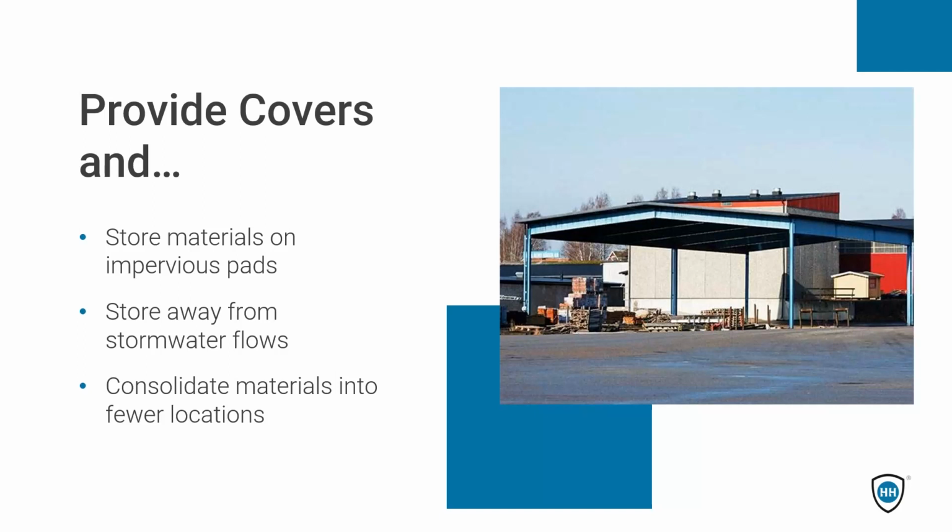For example, containers that are stored outside, portable tanks, generators, equipment that is just commonly messy. Anything that you can provide cover for is going to help you prevent it from being affected anytime that it rains or anytime you have a large snowmelt event. So look for things that you can put in place.